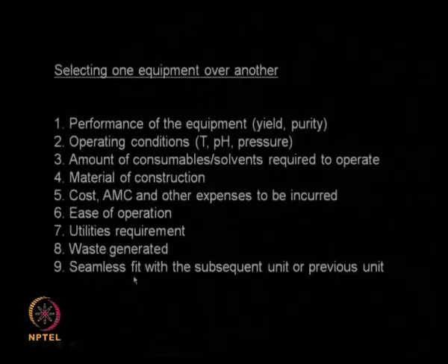If I am doing a unit operation at a high pressure and the next equipment is at low pressure, I need to bring the pressure down so that I can do it in the next equipment. So that is not a very comfortable fit. That is why it means seamless fit. If the pressures in the subsequent units are similar, if the temperatures in the subsequent units are almost similar, not exactly, then I need not spend extra energy to bring down the temperature or change the pressure. That is what it means as seamless fit.